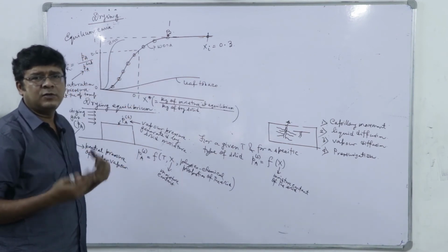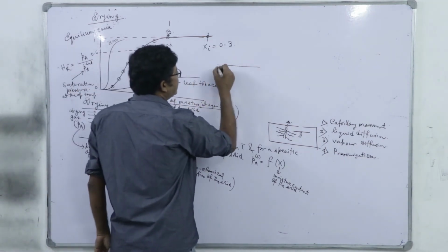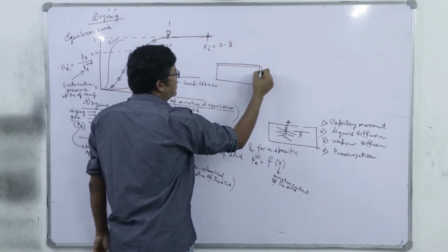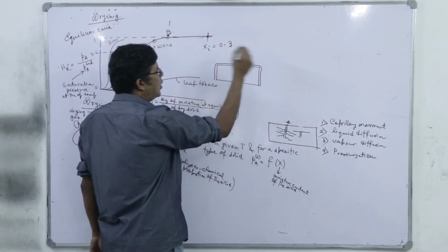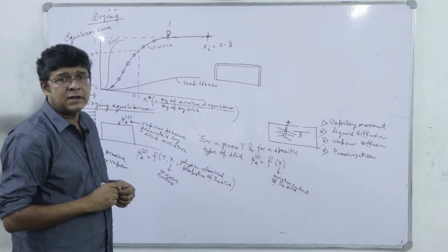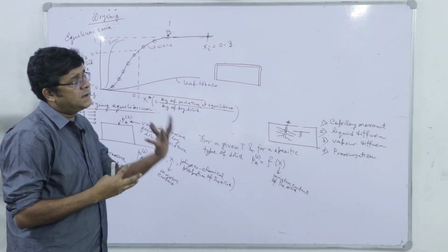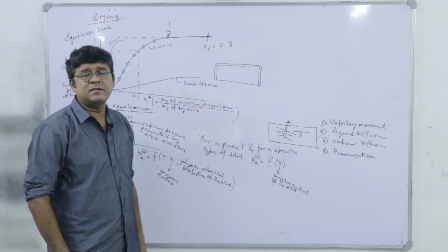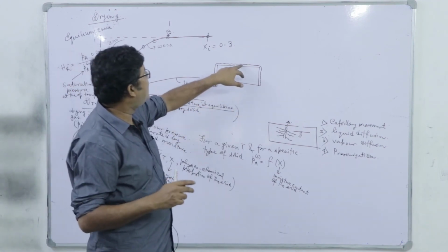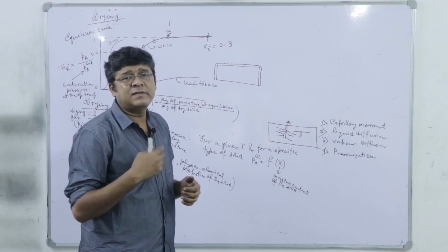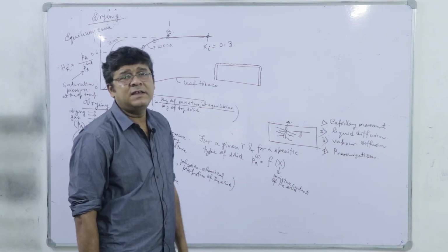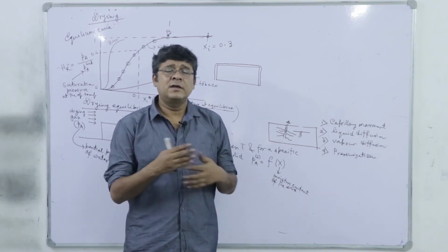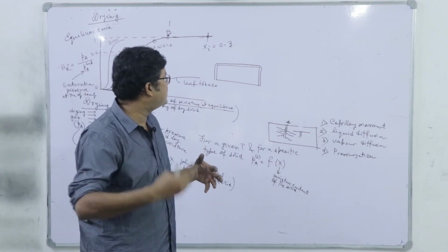The wood will progressively lose the moisture, but initially we have to note that when the moisture content is 0.3, definitely there will be layers of water existing over the external surface of wood, which is not being held tightly with wood by means of physicochemical interactions with wood fibers, because the film thickness is in the order of millimeter, whereas the interfacial force that is typical, the DLVO force, is a combination of van der Waals force and electric double layer force, which acts between the surface and these ions.